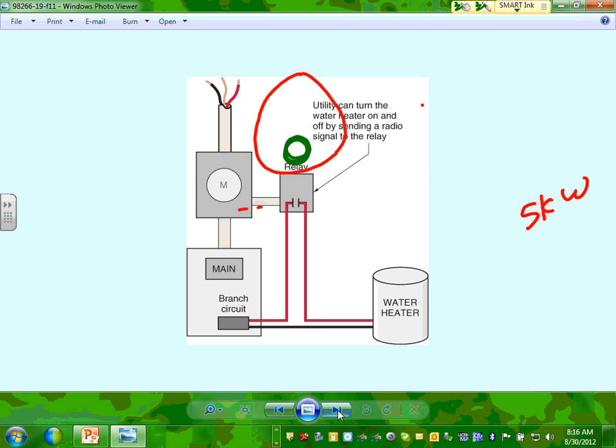Another thing, guys, they do, and this is typical for air conditioning and could be for water heaters, is the utility will come over here and you feed your 30 amps right in here. You bring one of the hots into a relay, and this relay is controlled by radio signal. This is typical for air conditioning. I have this one in my house. They come and set it up for you outside for your air conditioning. And when it peaks, only when it peaks, they control it.